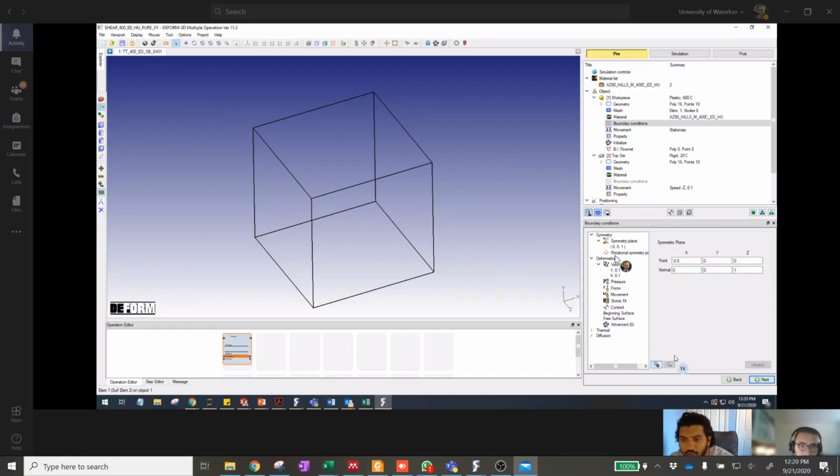Okay, click add, because you've manually text edited it. Oh, so I think it's just showing you the direction here, maybe. You're saying, why is it showing you 2 nodes lit up? Yeah, I guess, okay, whatever. It says normal about the symmetry plane, right? And this is the symmetry plane. Yeah, I think that's okay, don't worry. Just set up the rest of the boundary conditions and run it. If it makes a difference, then we'll go back and look at these in more detail, but let's just make sure it changes the result.